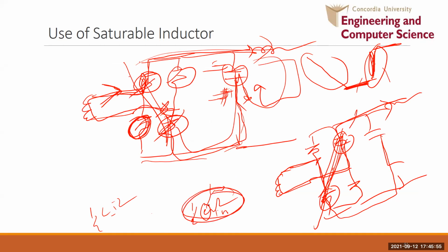So this will extend your soft switching range, because the energy stored is quite low. In other words, even if your converter enters the hard switching region, the energy storage is quite low, so the losses due to hard switching are less compared to silicon devices.